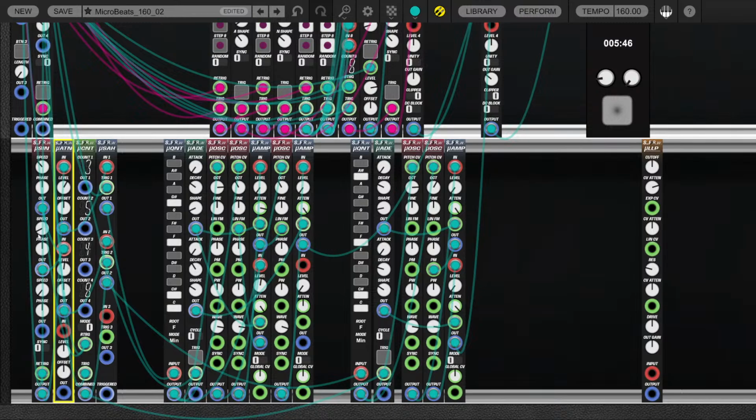In that case, I'm connecting 2 channels of the sine LFO instead of the combined output, just to have a different modulation signal. I have to be careful here now, because both of these outputs will output signals from -5 to +5 volt. So I need to adjust the attenuator accordingly and turn it down a little bit more than the attenuator here at the top, which received the common output of the sine LFO that is scaled for all 3 sine outputs, so it is still in the range of -5 to +5 volt.